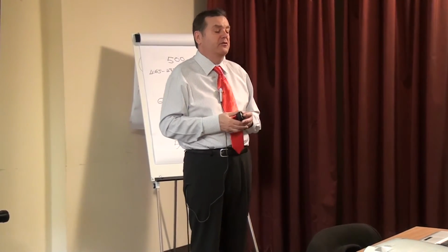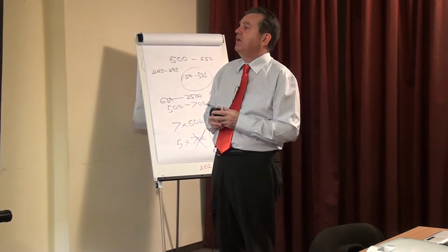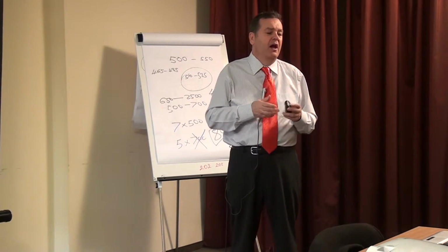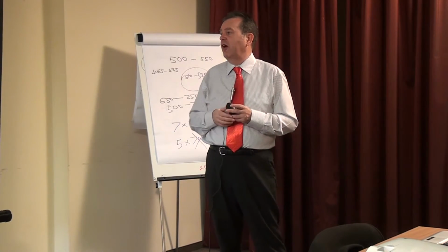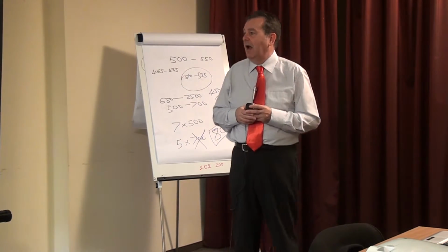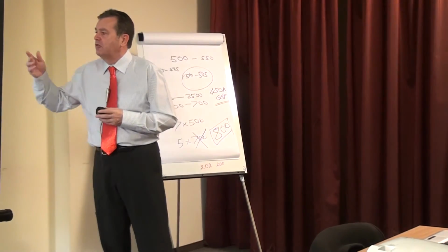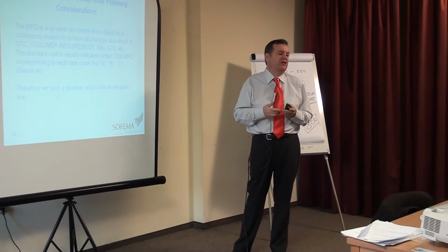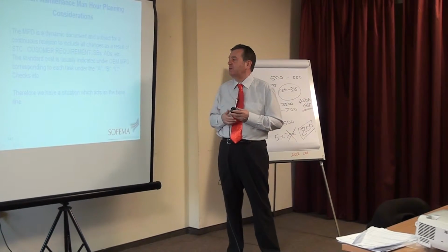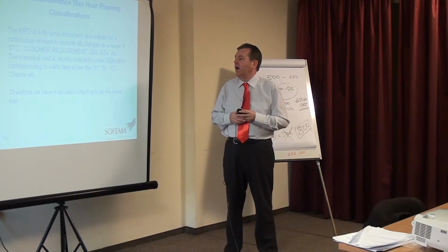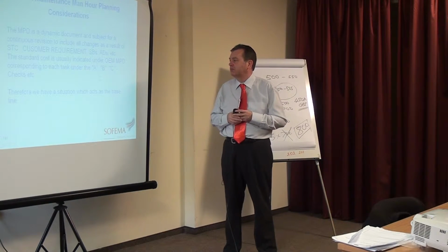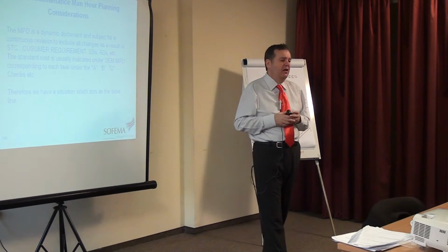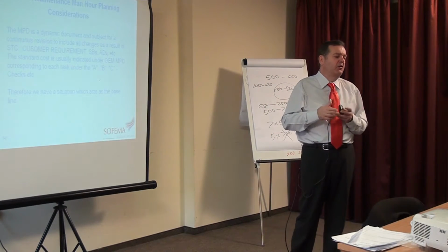But that sometimes happens. The MPD is a dynamic document. We've spent a lot of time talking about the MPD, and we know that it's subject to continuous revision, and it pays attention to changes that can come about from STC, from customer requirements, from SBs, from ADs. When we talk about standard cost, it's indicated under the MPD corresponding task.